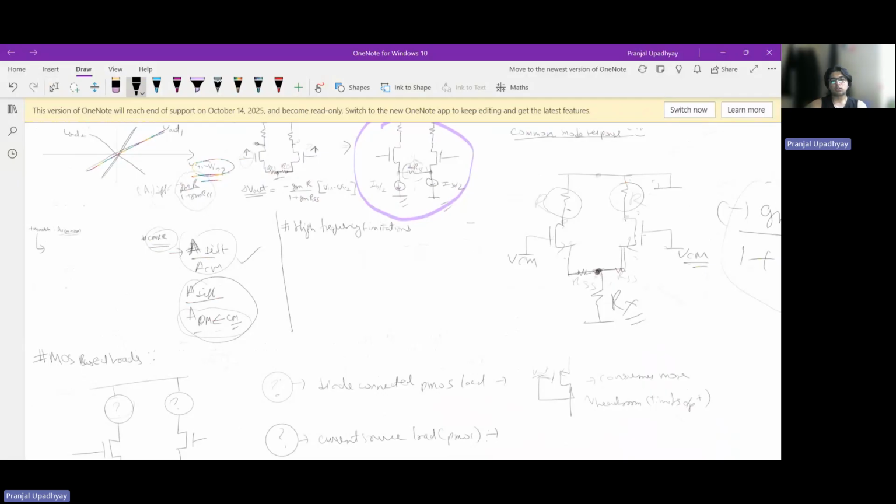Common mode to differential mode conversion is way more problematic for us, especially when we are taking a fully differential output. However, the desire to keep the normal common mode gain low is also always underlying in our differential amplifiers, whether it be single-ended, double-ended or fully differential. So let us talk about this also.